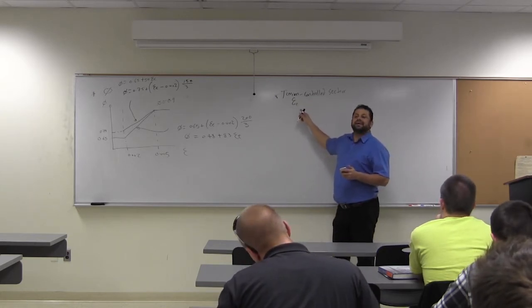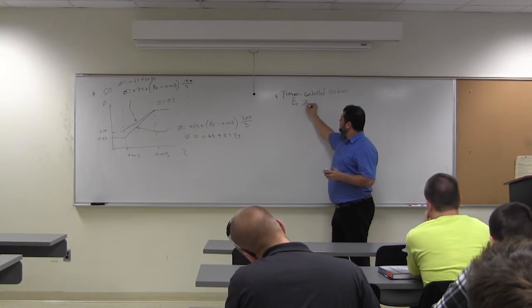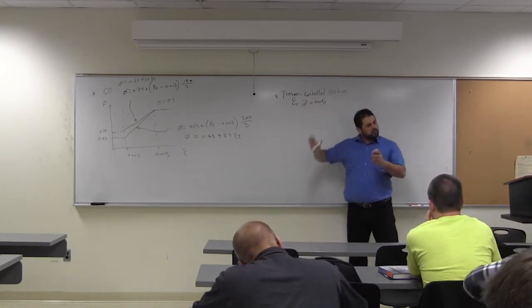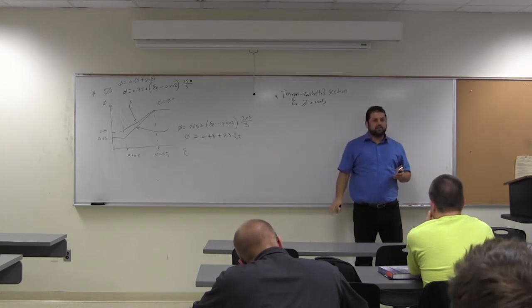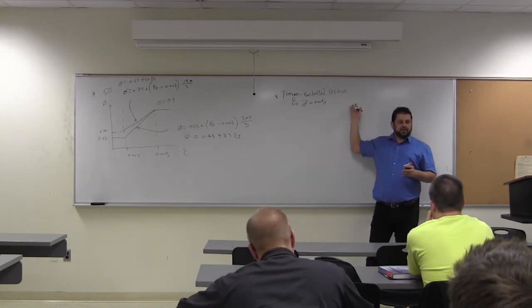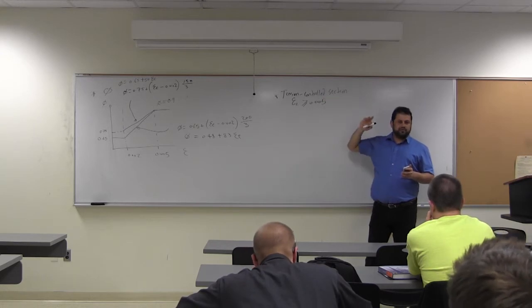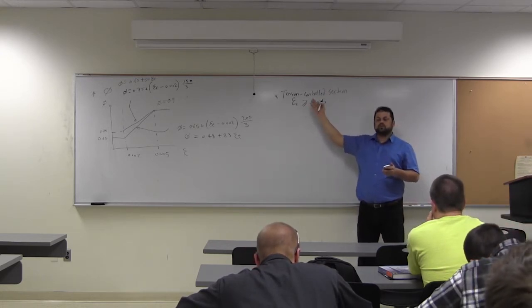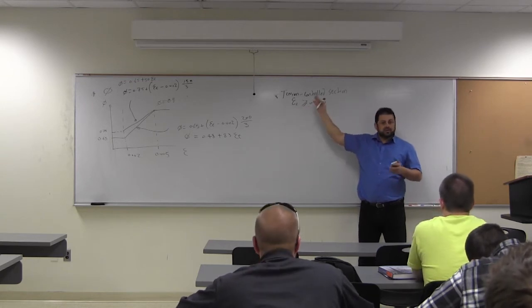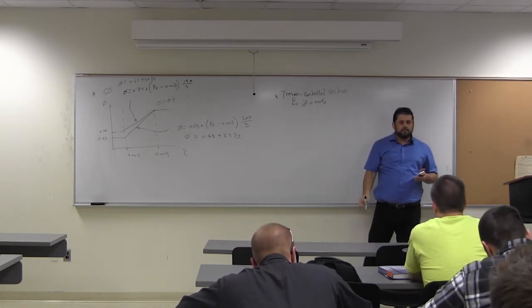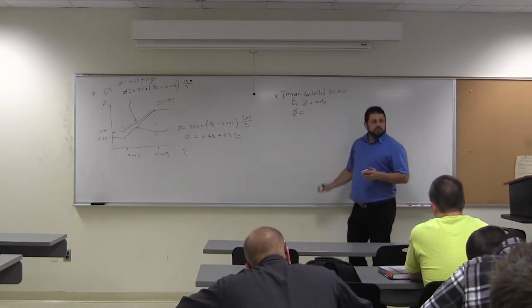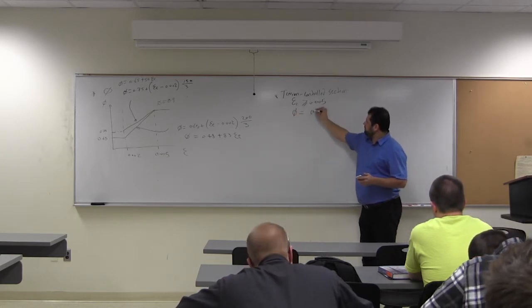Greater or equal to 0.005, or at least 0.005. What else do you know about this failure mode? That's a good failure mode. The ductility is at least 2.5, which is 0.005 divided by epsilon y, which is 0.002. What else do you know about this? The Phi factor is 0.9.